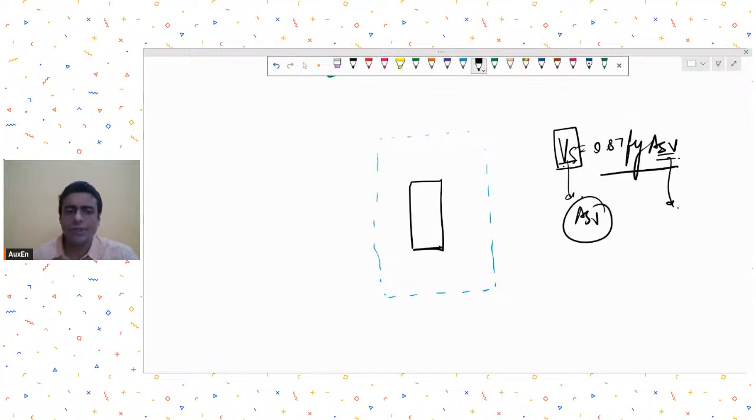Now this area of steel, we can distribute it as single bars in plan view like this. You can proportionately distribute it along the d by 2 closed perimeter. So something like this.